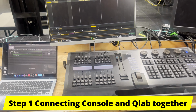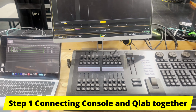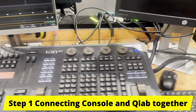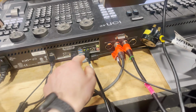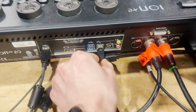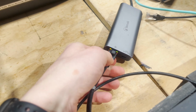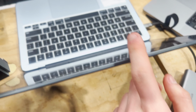Step 1. Connect the console and QLab together. In order to connect the console and QLab together, we need to use an Ethernet cable. So if we head around to the back of the lighting console, we see that there are 2 network ports. We're going to plug this Ethernet cable into port 1. And then the other end of that cable is going to plug into my USB-C to Ethernet adapter, which is plugged into the QLab machine.